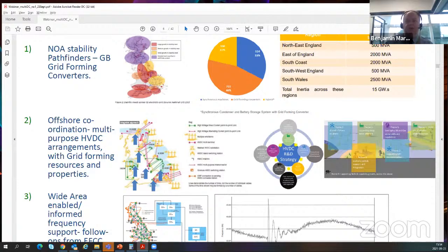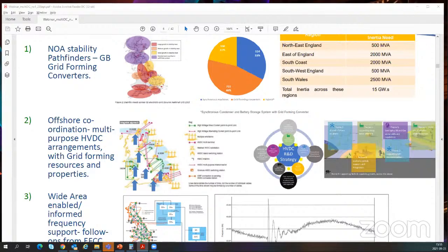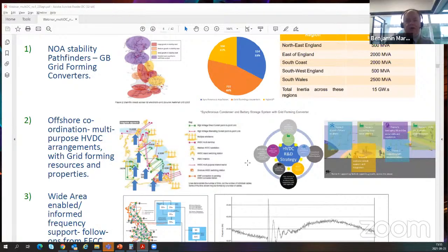So the use of grid-forming technologies surrounding those converter penetrations becomes critical. It's about making sure that the wind farms and indeed the converters themselves are providing this grid-forming capability, to ensure that you have the ability to slow down the onshore AC system frequency and coordinate your resources. Where I've put the blue arrows are the key locations where large converters are coming onto the GB system, which just so happen to be locations where you would have in the past seen very strong anchor points of large traditional inertia on the network. So you can see there's a coincidence, there's an opportunity that we need to agree on. And part of the delivery of these solutions, when you've got a large contribution of inertia, whether it's from converters or in the case of conventional products, is that the conventional tuning becomes different.